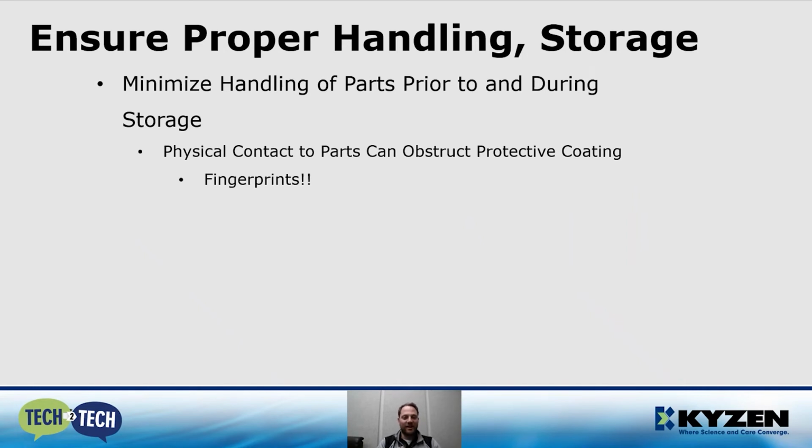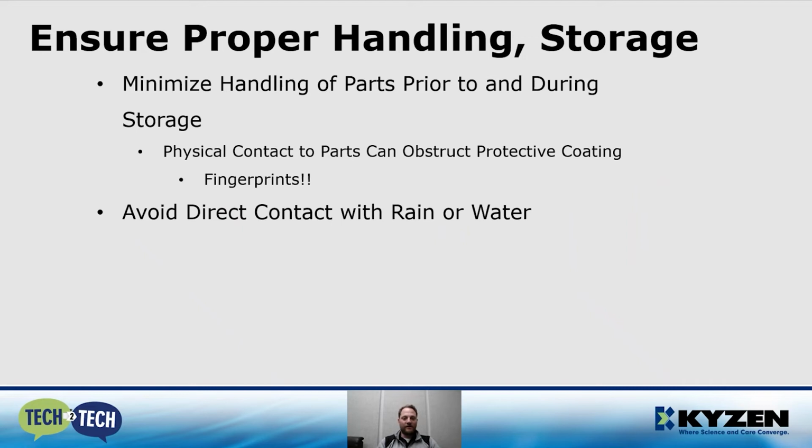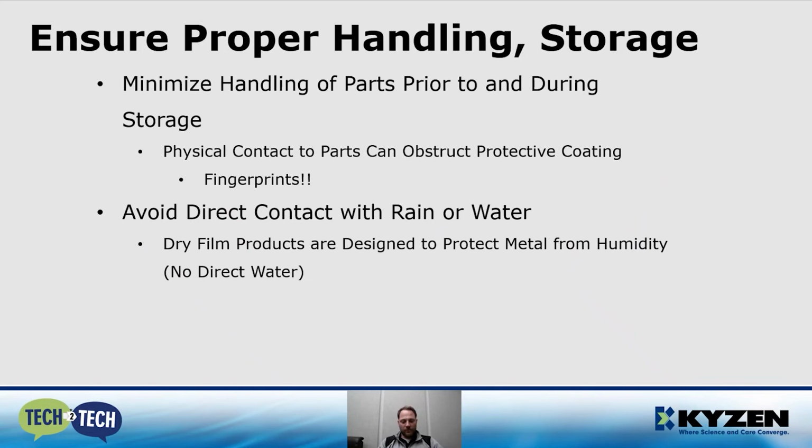And if people are handling the parts without gloves or something like this, a lot of times you'll see a little rusted fingerprint in the surface of the parts, and it's pretty easy to figure out who the operator was that was doing that. Avoid direct contact with rain and water. This is key. RP is not really designed for direct contact with water. It will rinse away. The amount of protection that you can expect will be significantly degraded.